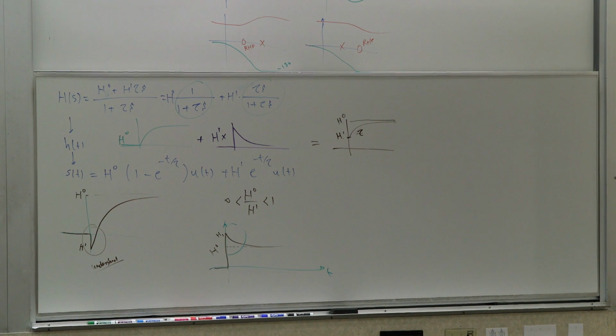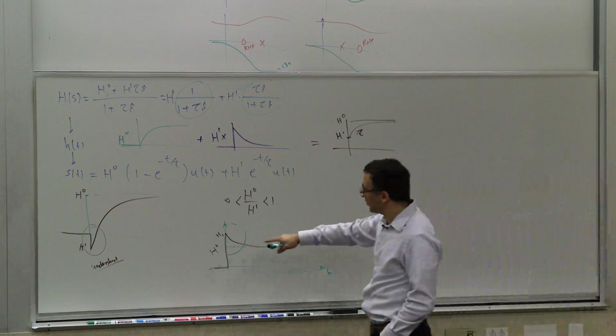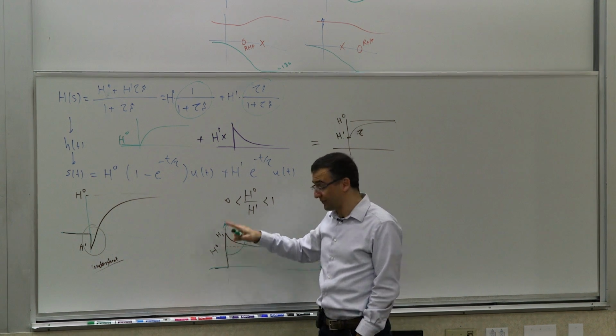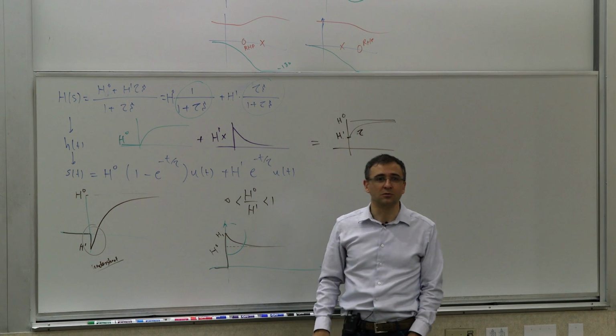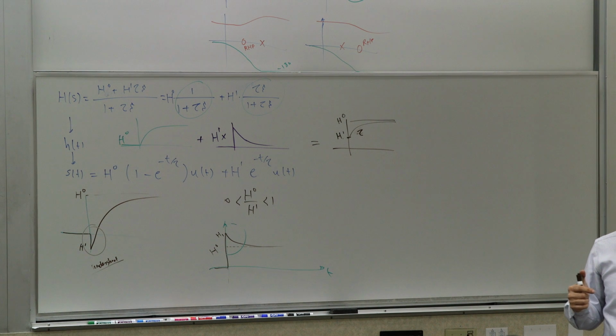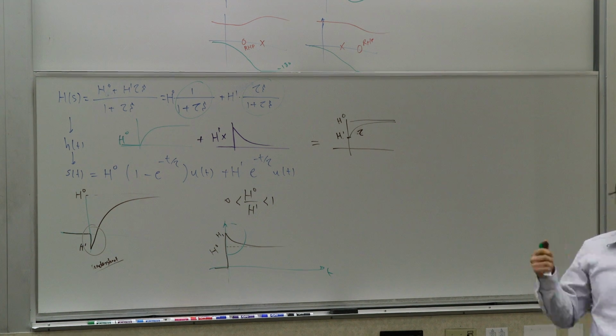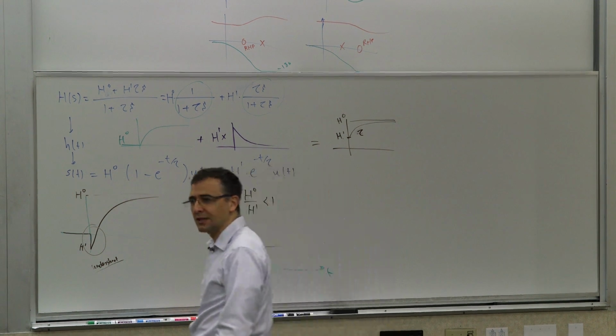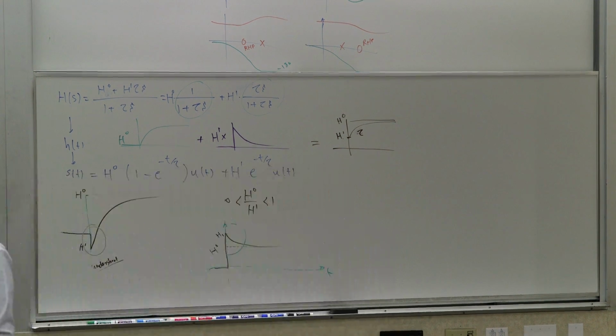It's kind of a funny looking overshoot right now, but even if you have a higher order system, which may be a damped system from that perspective, the 0 can do this to you. This is something that's usually overlooked. A lot of people assume that you need to have a second order system to have overshoot. Not true. You can get it through a 0 in a first order system.